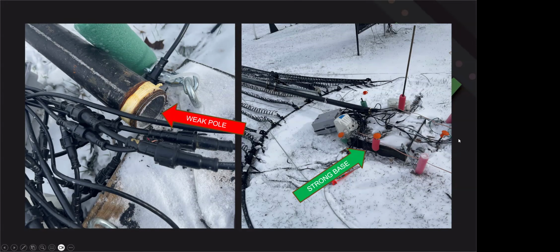You'd never see a threaded connection being counted for any bending in any real structural engineering purpose. It's not a good idea. Avoid it if at all possible. If you can't avoid this, if this is all you have, make sure you have guy wires on there that are very, very strongly connected that aren't gonna pop out in any way. This looks like this was one of the guy wires hidden under my arrow there. Probably came out, led to the entire failure on this.